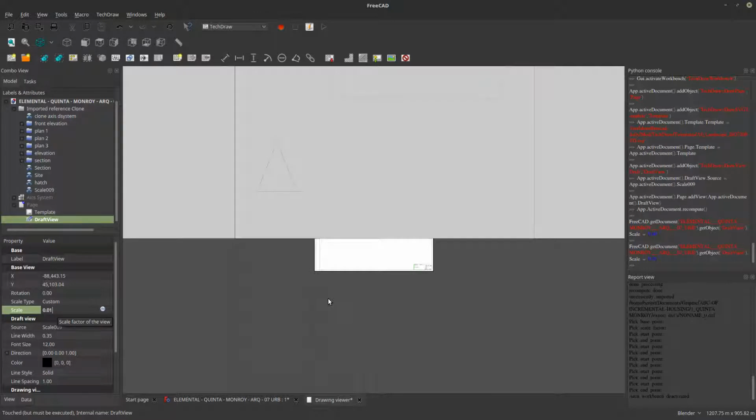So what you want to do is make sure that FreeCAD uses only its own lines, the lines that it understands, it knows, because those have a much better chance of being much cleaner in terms of the amount of nodes, the amount of points, whether the line itself is a duplicate or not, all those parameters. So if your drawing is very clean and very lightweight, then you won't have this kind of problem. But clearly this